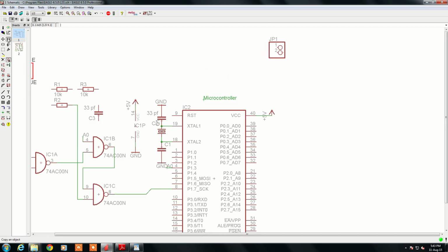I will copy the VCC symbol and copy the ground symbol. Now rename it as a connector for supply. So now this 2-pin connector, you can use it for connecting wires or some connector, so that it will be used for mounting the berg strip male, so that with the help of a female connector you can connect it to the power supplies.